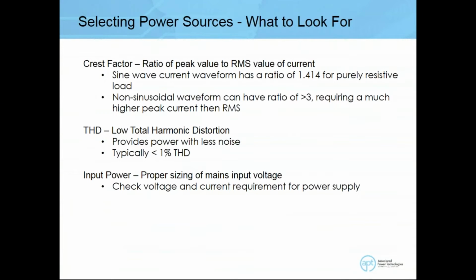Crest factor. When we have non-ideal loads, non-ideal loads would skew the sine wave in such a way where the peaks are much higher versus the RMS value. So when you have a much higher crest factor, you want to make sure that the power source is capable of driving these loads.